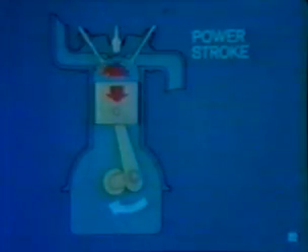The third stroke, then, is the power stroke. Combustion is already well in progress as the piston starts down again, with all the pressure of the expanding gases pushing the piston to drive the crankshaft. Near the bottom of the power stroke, the exhaust valve begins to open. As the energy of the burned gases is used up, the exhaust gases must be removed from the cylinder.